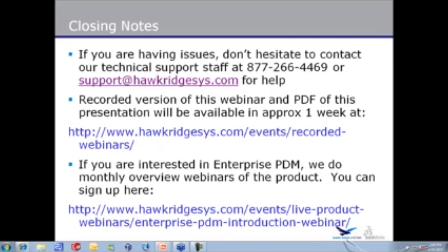Let's see. Couple questions. Michael, using SOLIDWORKS Explorer on Windows 7, can't see the Vault. That's probably a simple issue of just having the add-in turned on or off. Again, I'd suggest calling our tech guys and they can work you through that. With validation on restart, is the service technically not running while validating? Not technically, Henry. When you're validating, the service is running because that's what's performing the validation. It's just not going to allow users to log into the system until the validation is complete.